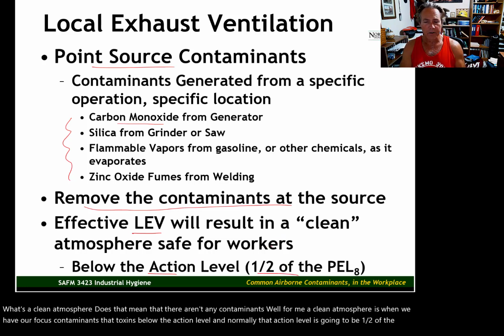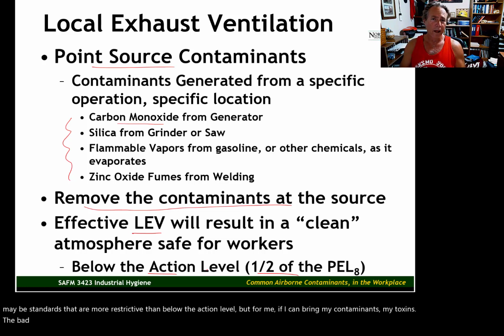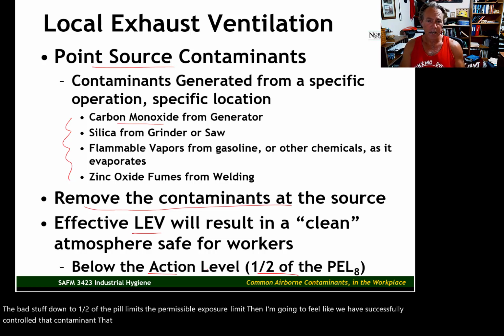Now, there may be standards that are more restrictive than below the action level. But for me, if I can bring my contaminants, my toxins, the bad stuff, down to 1/2 of the PEL, the permissible exposure limit, then I'm going to feel like we have successfully controlled that contaminant, that we've successfully exhausted that contaminant from the work area.